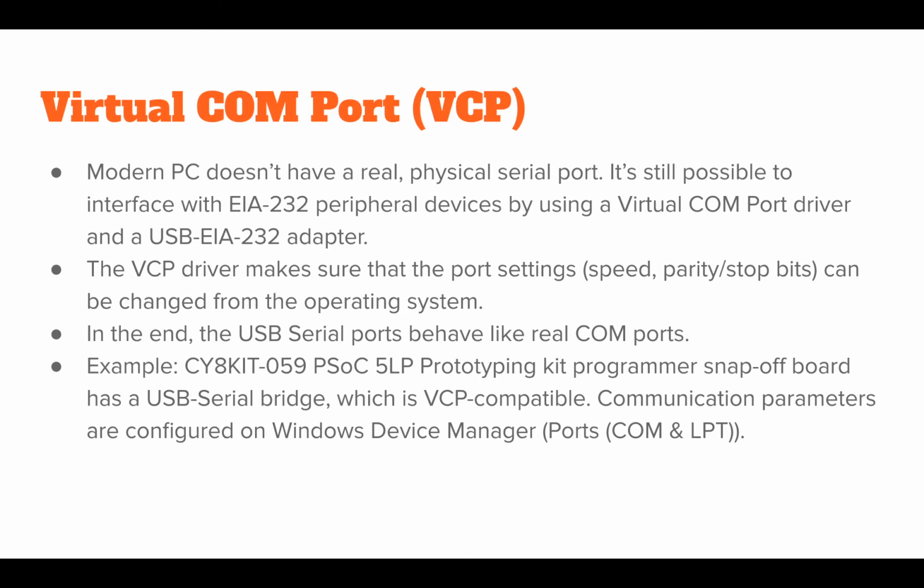USB has basically replaced the serial port, serial lines everywhere. But anyways, this protocol has not gone anywhere. For example, it's common between processors on a single printed circuit board, so that they would actually use the COM port or UART for the data transmission. It's still a valid protocol, not just between big devices and computers anymore, except of course if you have an old device.